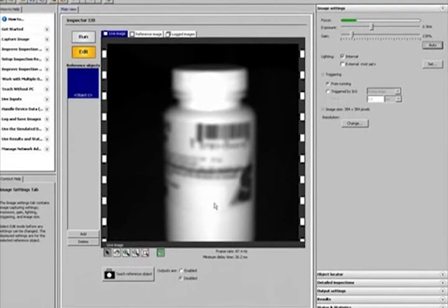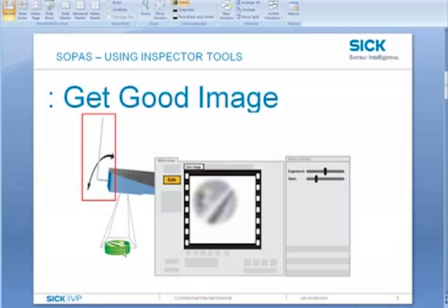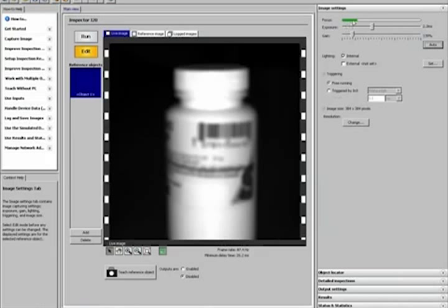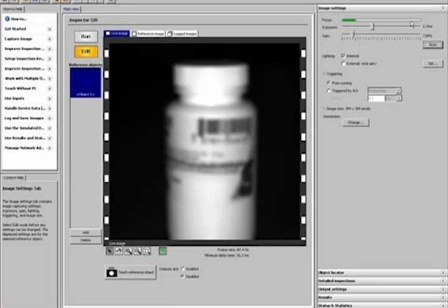So in order to adjust my focus, I need to use my Allen key tool and adjust the potentiometer knob found on the top of the unit itself. And when I do that, mechanically, the green bar over here on the top will expand or extend to the right as my focus starts getting better. So try to notice that change over here. When the focus starts getting better, not only can you visually see it, but you can also see the green bar, or the inspector telling you that your focus is starting to get better.